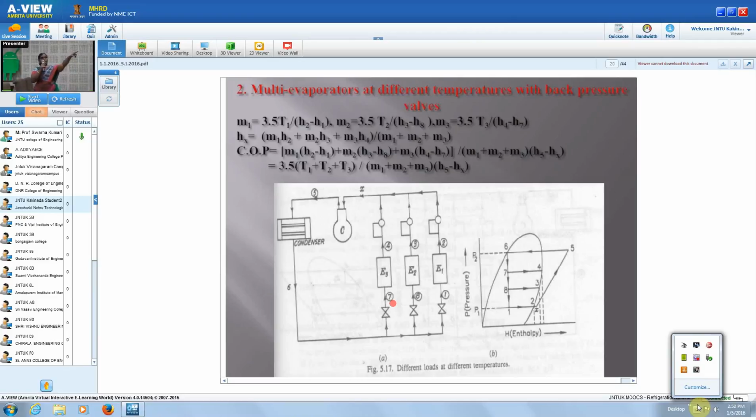So that is the refrigeration effect produced, that is shown in the p-h diagram. Similarly, at 6 the refrigerant goes into the second expansion valve. Then from 6 to 8, so 6 to 8 is nothing but the expansion in the second expansion valve to the required temperature in the evaporator here. So at that, 8-3 is nothing but the actual refrigeration effect produced in the second evaporator.